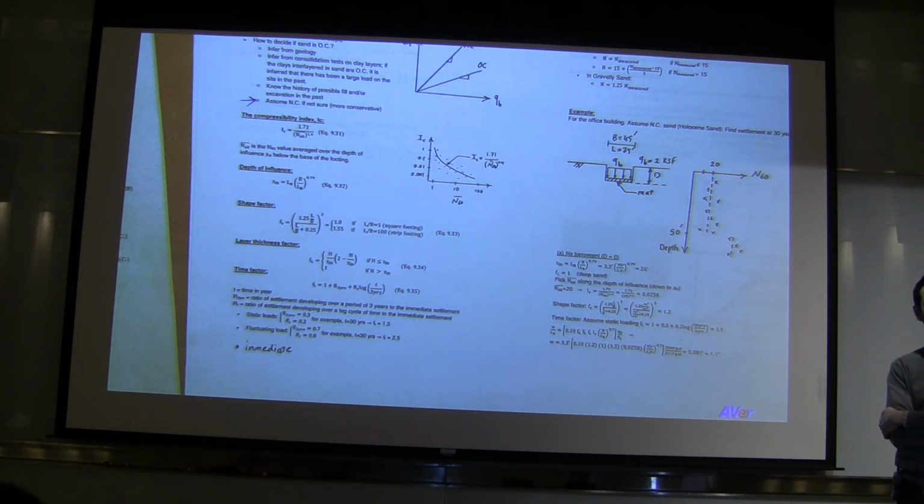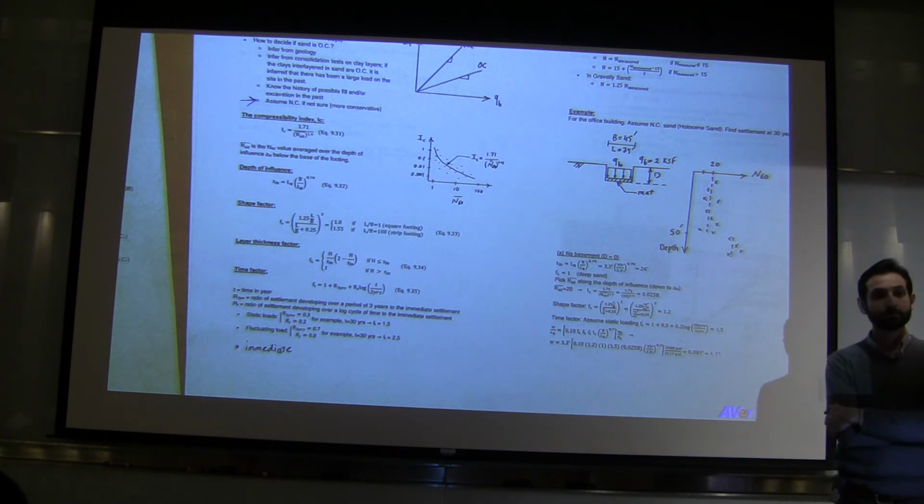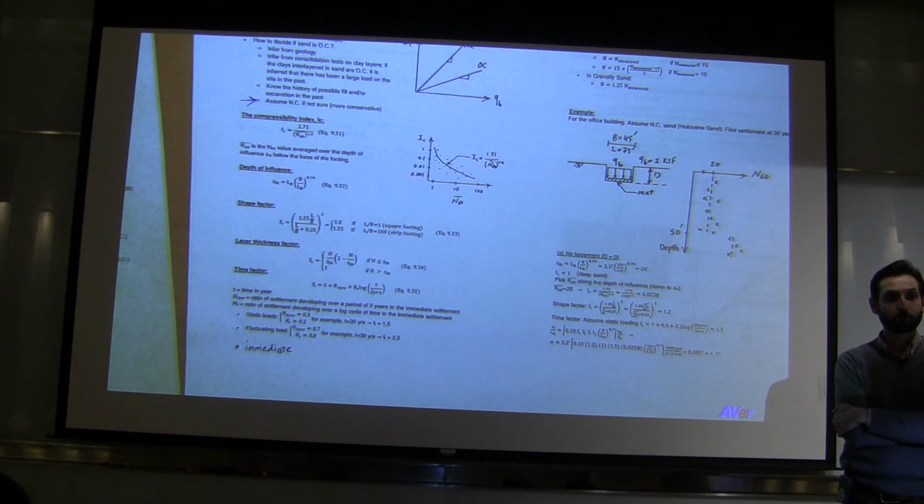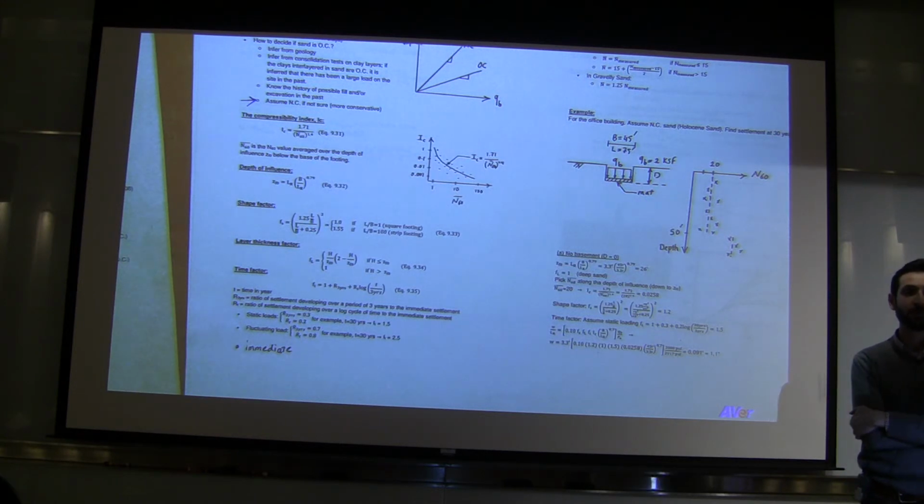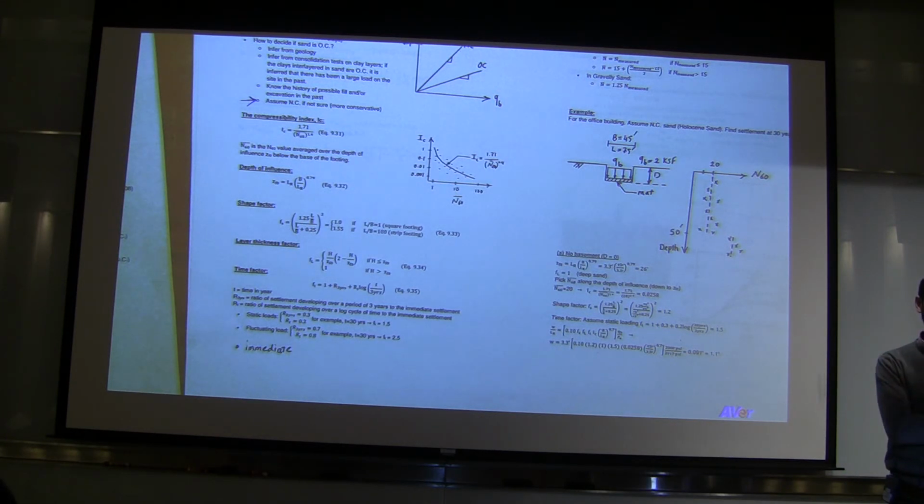Is that a situation where the loads are fluctuating, but the amount of load relative to the structure is essentially inconsequential or small enough that you can neglect it? That's a very good point too. For most structures, we have a dead load or a static load that doesn't fluctuate, and then you have a portion of the load that does fluctuate. So the question becomes, do you have 10 kips of static load and 10 kips of dynamic load, which is significant, or do you have 100 kips of static load with 1 kip of dynamic load? In that case, it doesn't really matter.